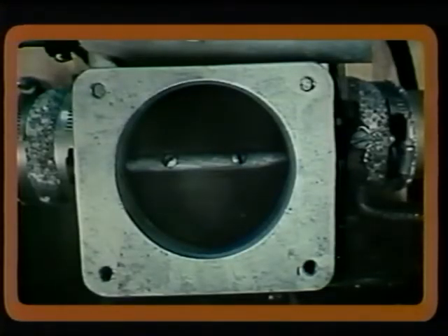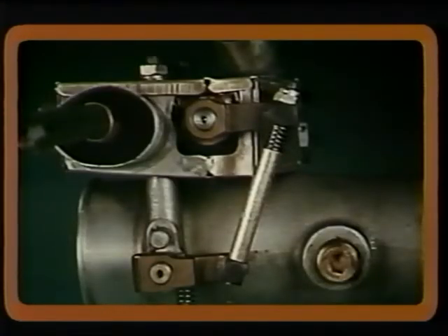As with all of the types of pressure fuel metering systems we have discussed, controlling the closed position of the throttle air valve determines the idling RPM of the engine. And by varying the length of the connecting rod between the throttle air and fuel valves, we can control fuel flow at idle, which controls idle mixture and smoothness of engine operation.